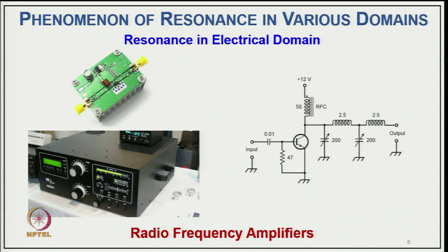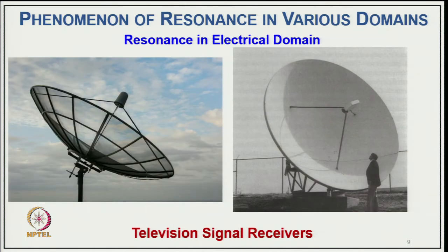It is used in a radio frequency amplifier, where you have a capacitor and inductor along with some resistive component, which is part of the inductor or otherwise put separately. It is used for the purpose of tuning the radio frequency corresponding to different stations. Then you have the television signal, so there we have the concept of resonance in the electrical domain.